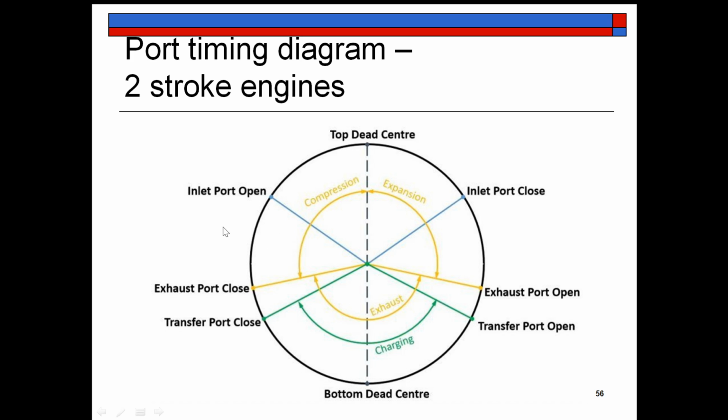The inlet port will open, the inlet port will close practically during the expansion stroke only, when the piston is coming downwards, but the transfer port will be opening here before the piston reaches the bottom dead center. You can recollect the diagram which I have shown in the previous session, and the transfer port closes before the piston reaches the top dead center further.